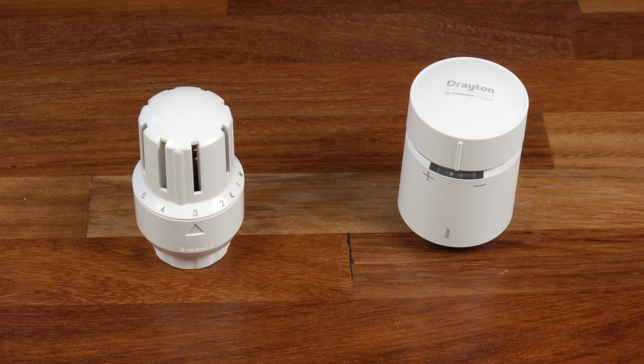So for my system, I'll be installing a smart radiator valve in the living room, which is at the front of the house, and the kitchen, which is at the back of the house, and then upstairs I'll install one in the main bedroom at the front of the house, and another in a bedroom at the back of the house. With this setup, I don't need to worry about the downstairs hallway having to get below a certain temperature before it fires the heating, because that's where the main thermostat is. If any of these individual sort of wider areas of the house start to get too cold, that's enough to turn the heating system on, and that'll fire up and heat the whole house up again.